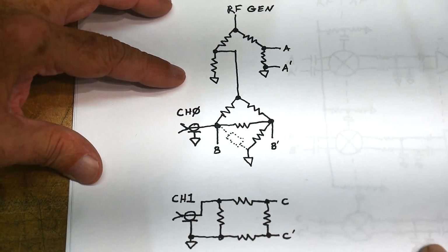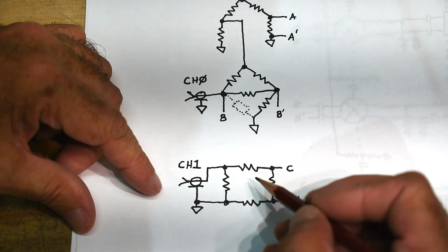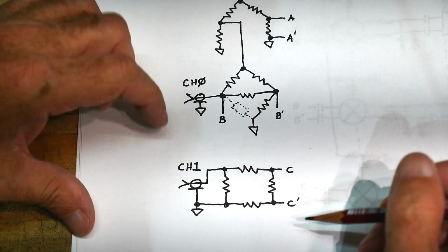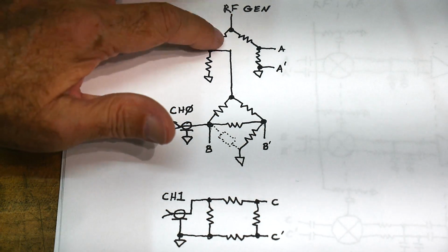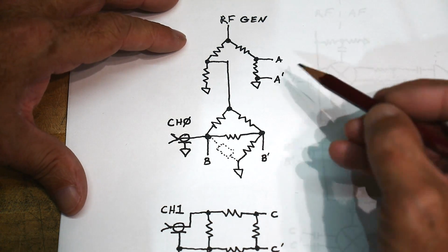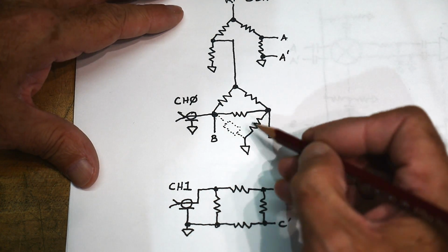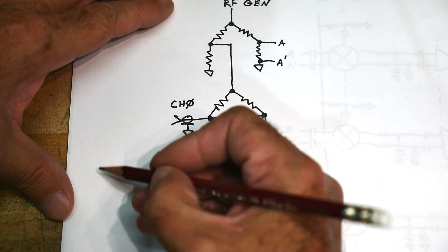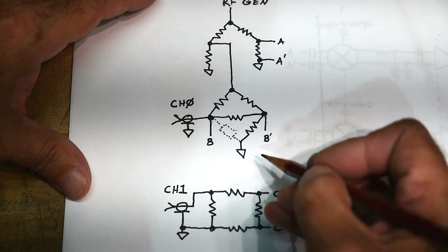All right, so what does channel 1 do? Channel 1 is input only. And so you need to input a signal here. It goes through an attenuation pad and then is measured, right? So there's 3 measurements, 2 channels, and we measure the incoming RF, so we know its amplitude and we know its phase coming in. Then it goes through the bridge circuit, and we know its resulting amplitude and its resulting phase. And then if that goes out and goes through some network and comes back into channel 1, we then know its amplitude and its phase.